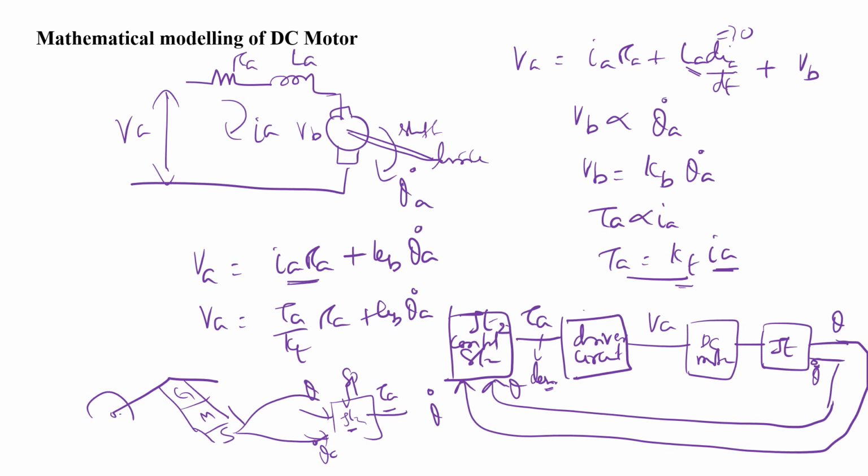In the driver circuit, we have a sequence: for t equal to 0 to 5 seconds you have to switch on this. For example, the windings are W1 and W2. For 5 seconds you have to enable this, and for the next 5 seconds you have to cut off the power supply and enable the other. This kind of logic is implemented in the circuit.